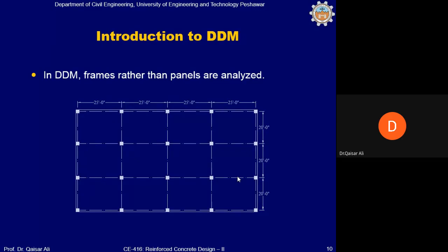So in order to maintain this space, if 9.5 feet is the space below the beam, and 1 foot is the drop of the beam, it will be added to this, along with the 6-inch slab. If all these things are added together, then a story height of around 11 or 11.5 feet will be needed.